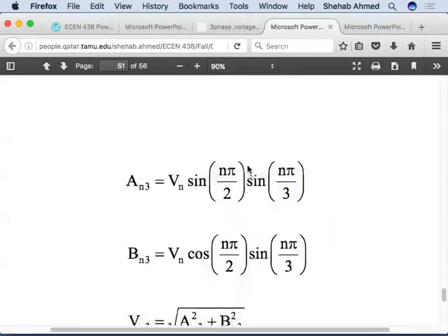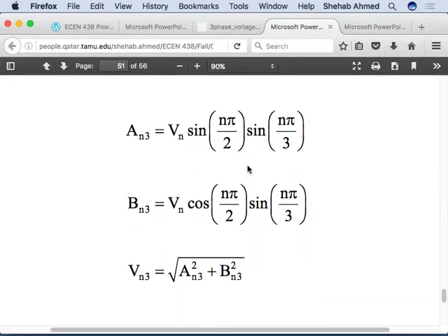Right? But sometimes your switching frequency for these high power converters is 500 hertz. 500 hertz is a very small value. I mean, when your fundamental is 50 or 60, and you're switching at 500 hertz. Right? It's a very low switching frequency. Some of the mechanical systems or the mechanical components, or even some of your electrical circuits, may have a resonant frequency around that much. And you want to make sure that you're away from the resonant frequency of any of the components that you have in your system.